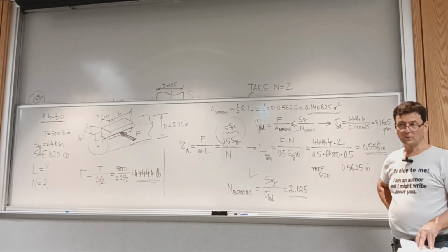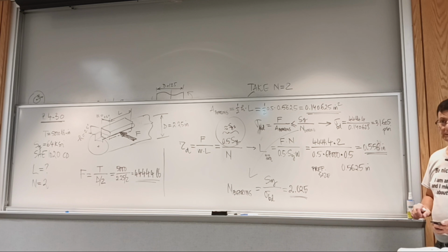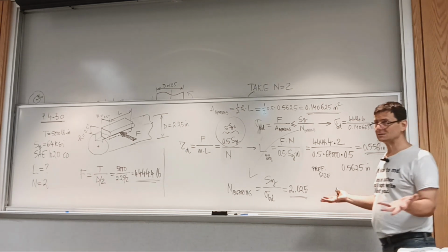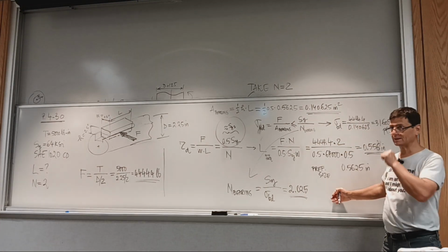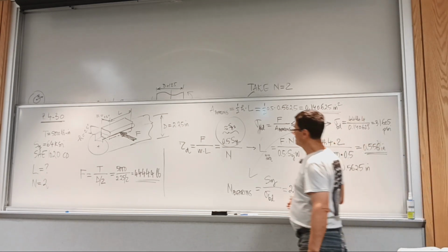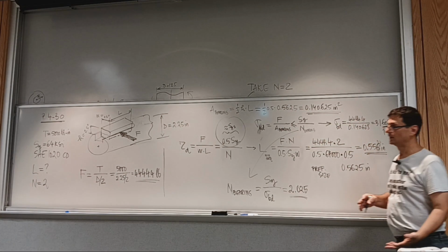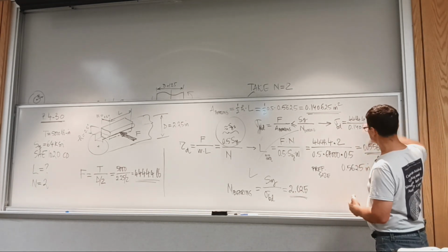So 0.9, what would that be as a design factor? You take the inverse of 0.9, that's 1.11. But that will be for buildings. Again, I'm teaching the machine design class, and we stick with 2 for both. So in terms of American Steel Construction recommendations, we are way over.